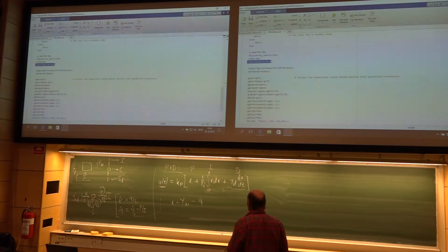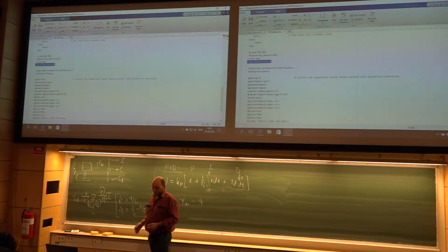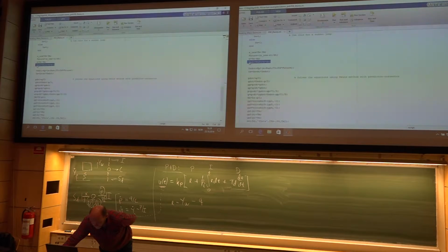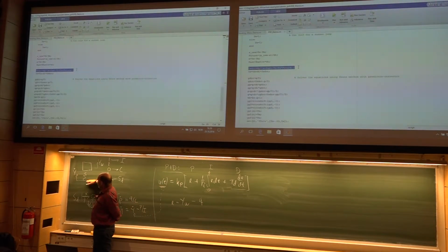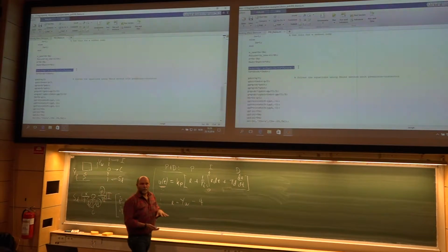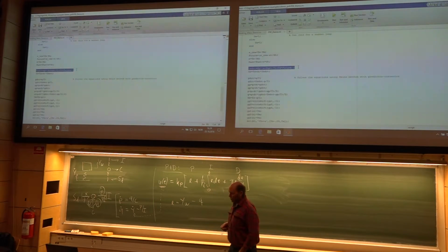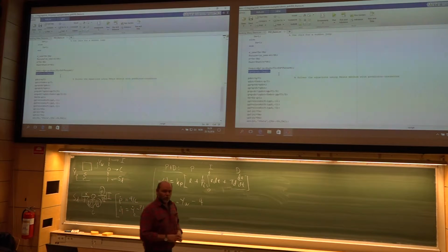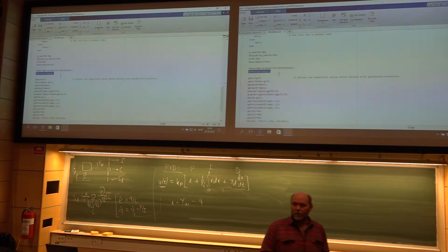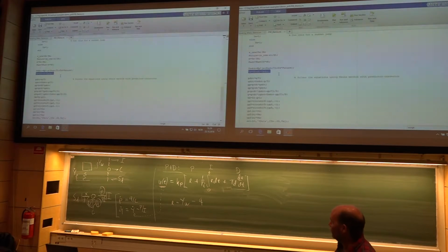Then I use this equation directly to construct now my y dot signal here. And having the derivative y dot, well, I also need the position for this plate to have the graphics in order to see how high the altitude is for the mass. So I just again use first order Euler scheme here, finding my new position based on the previous one and now the derivative. So this was my first attempt for a PID regulator.